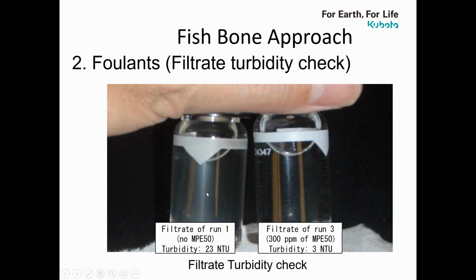If you have a lot of pizzas coming into the plant, and you don't treat that properly, if all this biology was dead, let's say, all this pizza is going to be left over. Soluble COD is going to be higher. Organic material is going to be higher. And you see a very white cloudiness, and that means the biology is not properly treating. So those leftover pizzas are going to start fouling the membrane.